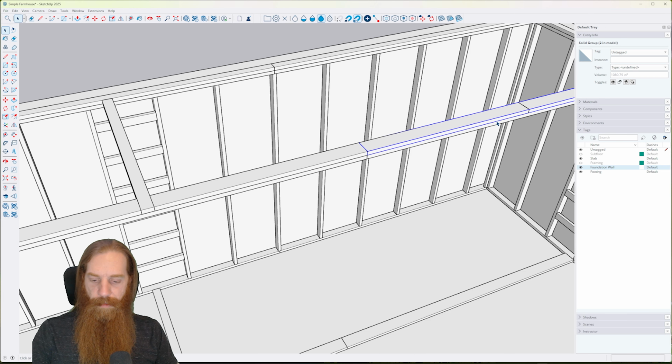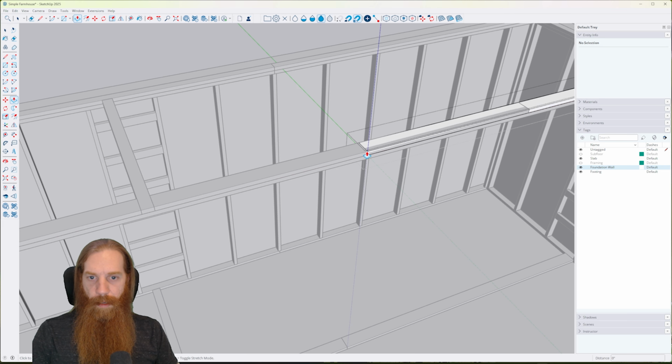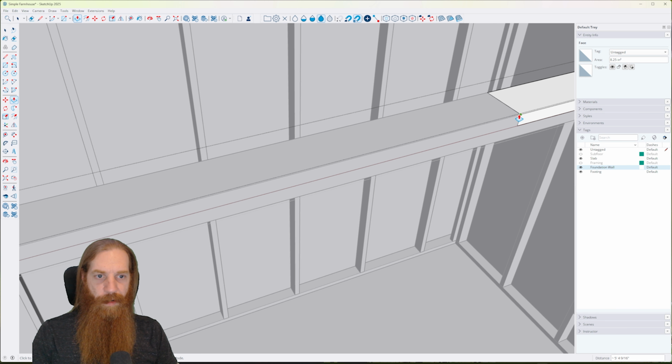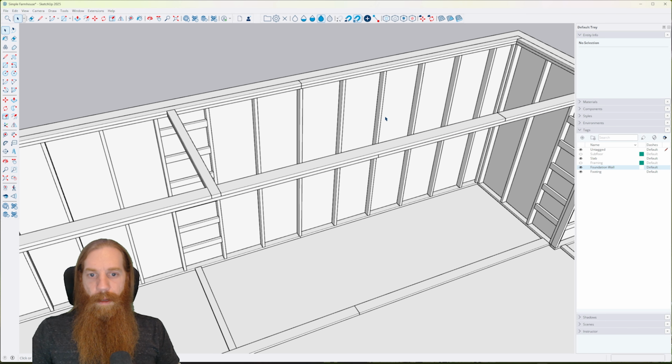No, what happened? I selected that. Oh, I got to double click it. And we're just going to shrink that one down to right there. Okay, it'll help if I zoom in a bit. And there we go. Now we have our seam offset. Let's see what the distance is between those. Over 5 feet. So we're plenty good with the seam offset there.